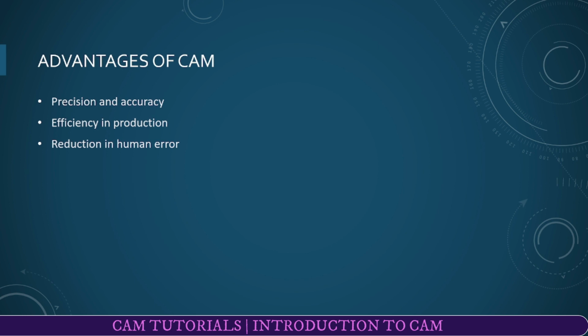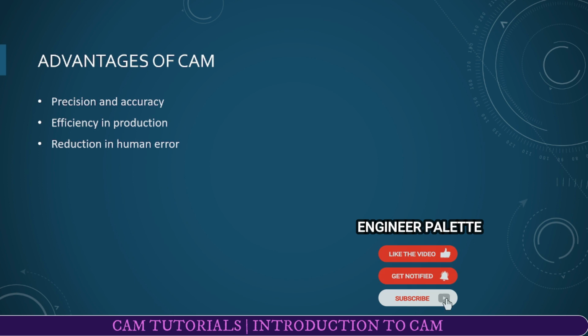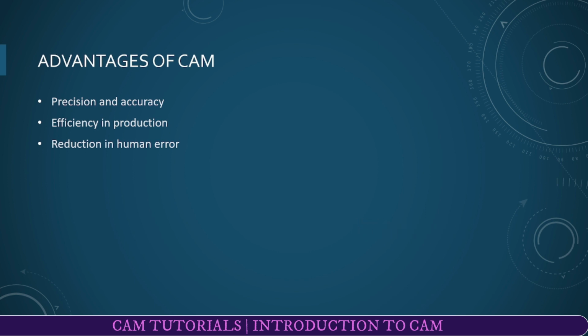In CAM they calculate thermal compensation and tool compensation and everything, and then they provide more precise dimensions and more precise tool paths to construct the part that you want, and provide more precise code that you can insert into the post processor of your CNC machine to produce your part.